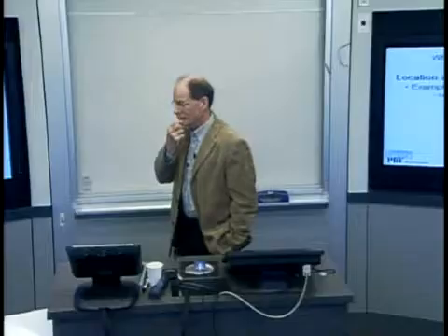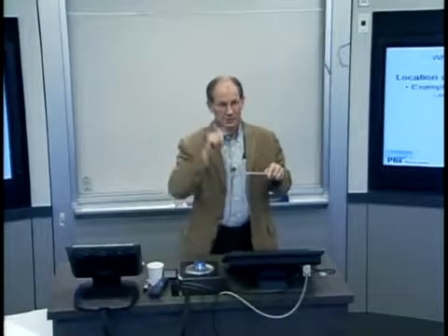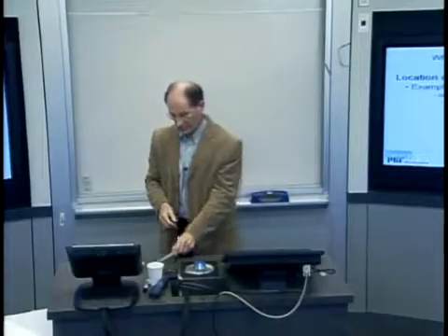So what controls the geometry change? Well, as you said, the local location and intensity of the energy exchange. So we already talked about this for turning, and here's just a schematic of a simple turning. This is actually the experiment we used to do, where you come in with so-called orthogonal turning and reduce the diameter of this stock.